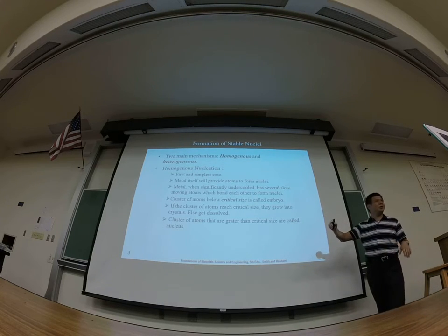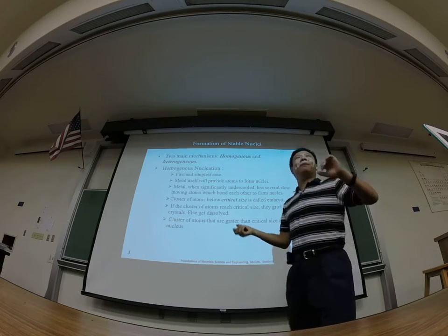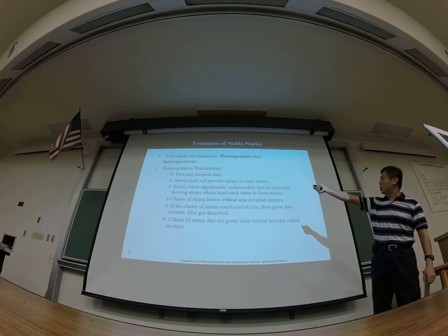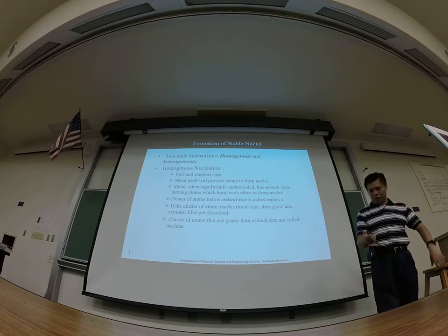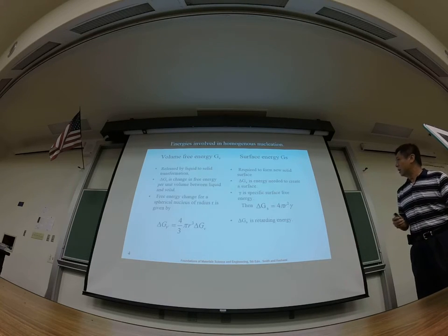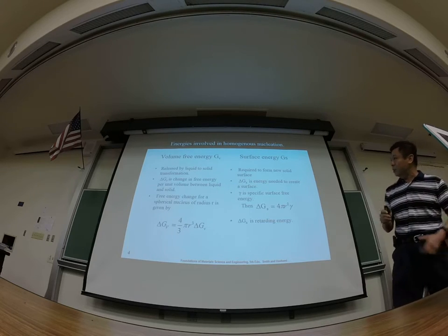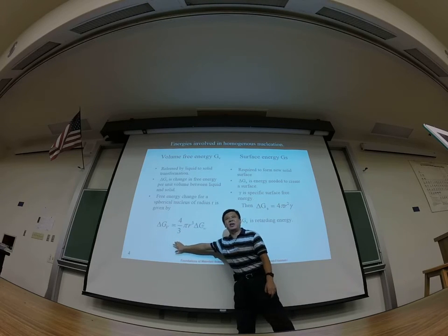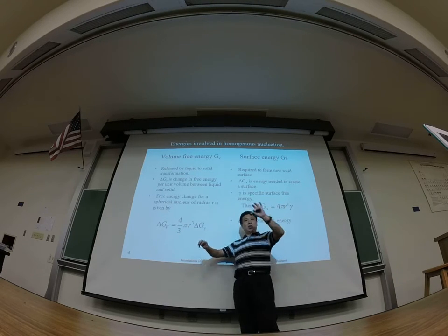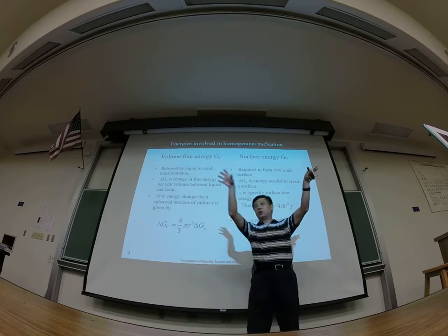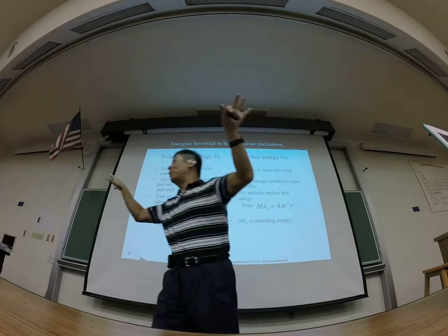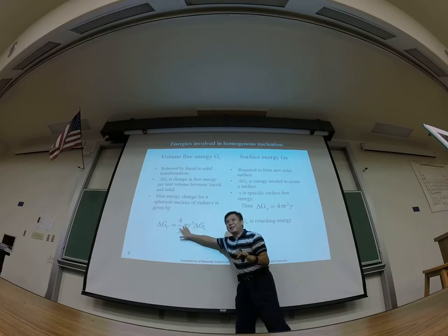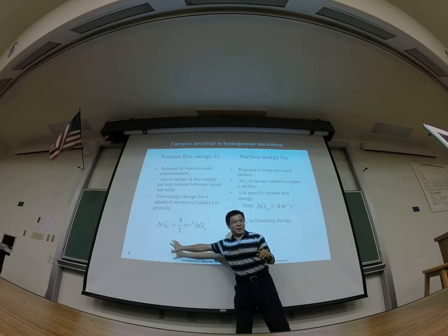And also we know that the simplest way to think about crystallization or solidification is homogeneous nucleation, right? So in that case, last class we talked about the two contributions, right? One is a free energy related to the phase change from the liquid to the solid, right? This process will release heat, so that means it will provide the energy for the solidification to occur.